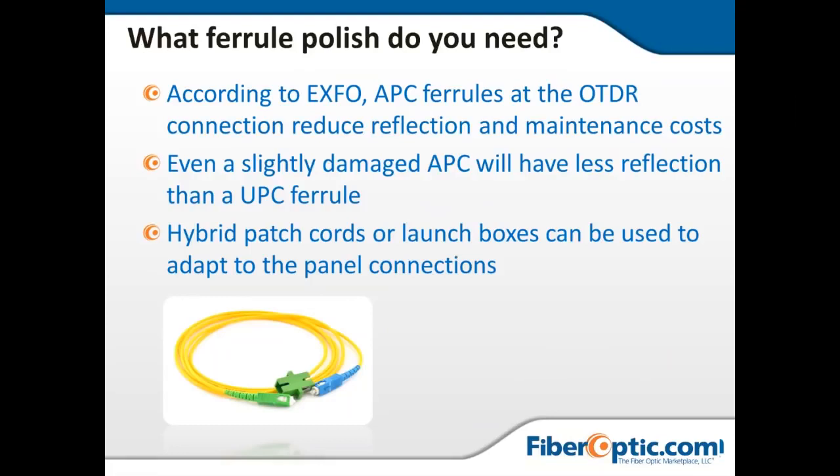Make sure you're looking at those bandwidths and understanding them if you want to do live monitoring of fibers. If you're doing DWDM, I really recommend you bump up to the 1650. Even though you get a little less loss performance there, because you start to tick up, it's still a relatively effective measurement, you can still get pretty good distance, and you also get a pretty nice separation from the other wavelengths we're operating under.